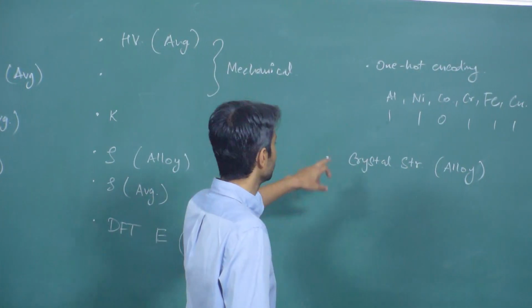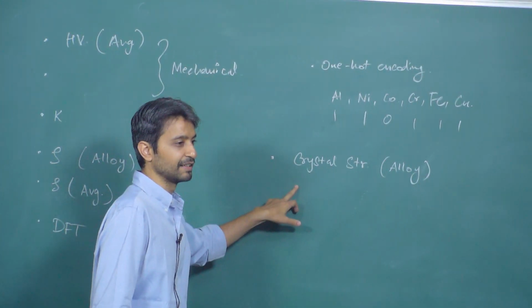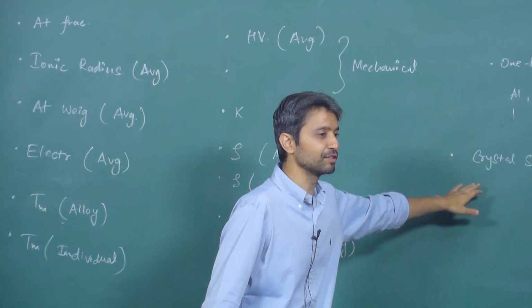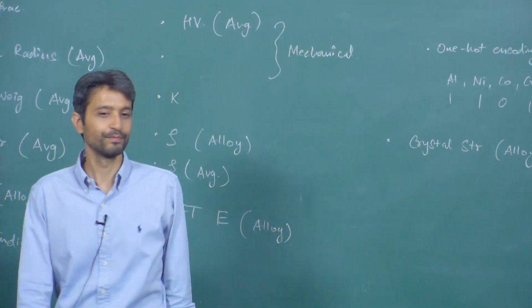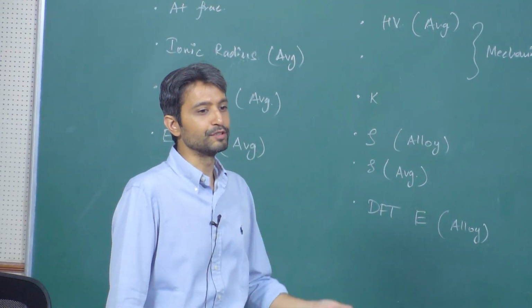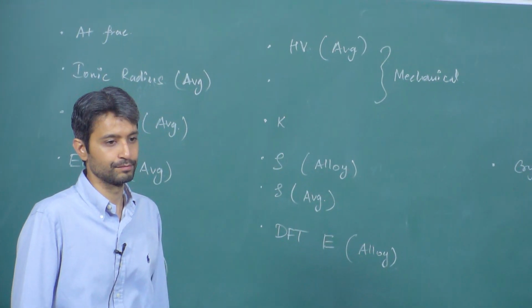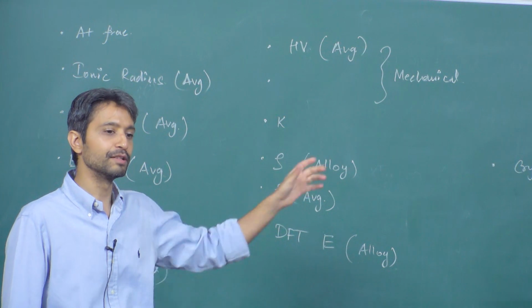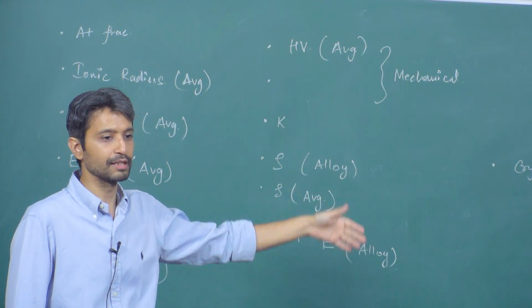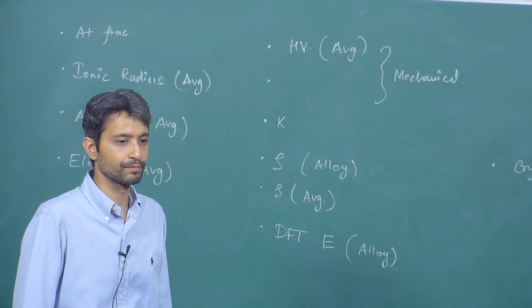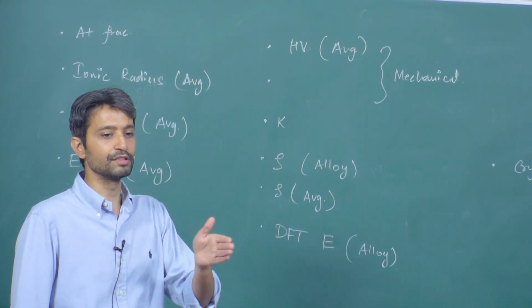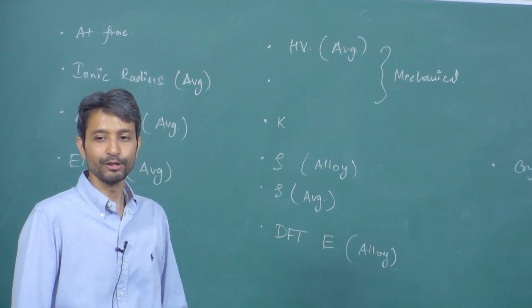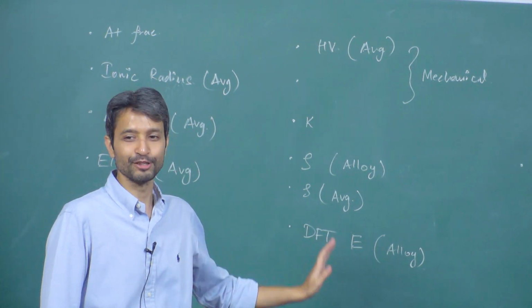Lattice, so crystal structure has that information. Yeah. So we mean crystal structure and associated features. Okay. Maybe you will represent the space group, or maybe you can represent it in terms of the symmetry elements which are present in the space group. Or it could be as simple as BCC, FCC, HCP. Yeah, atomic coordinates are tricky, we'll skip for now.